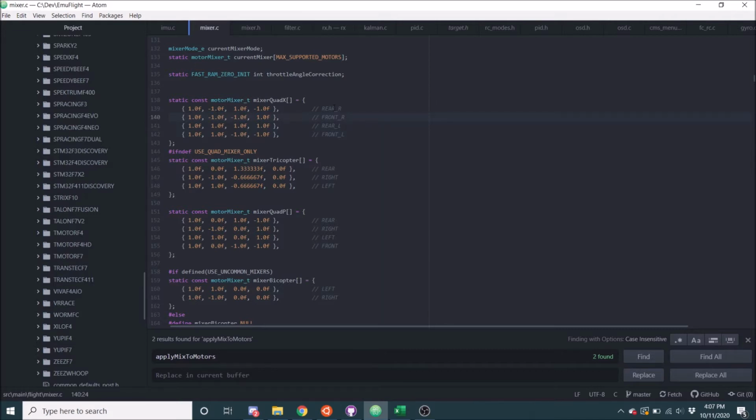And same for roll, you can see that the 2 right motors, they make the quad roll to the left, which is negative. So when you're given a positive roll, lower the motor output. And if we're rolling to the right, for the left motors, we want to increase the output. And same for yaw. It's quite simple. This mixer literally defines how the motors should act together in order to spin the quadcopter the way that we want it to, as well as mixing the throttle into there.